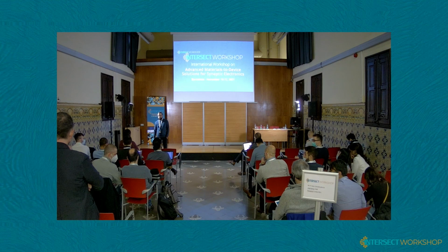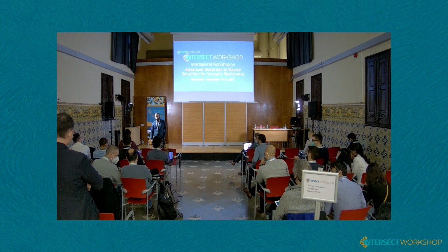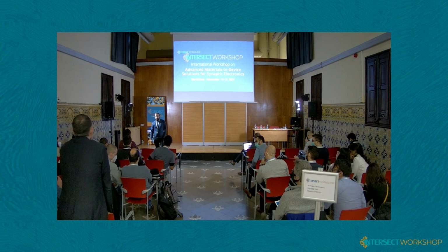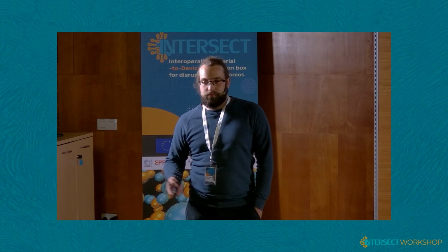And do these kinds of defects have any impact on the transport properties of the layer itself? If you measure, I don't know, the conductance, the Hall effect, the photoluminescence, how can you control this number? Is there any way to cross-check that? So you could probably measure with photoelectron spectroscopy or some other method, right?